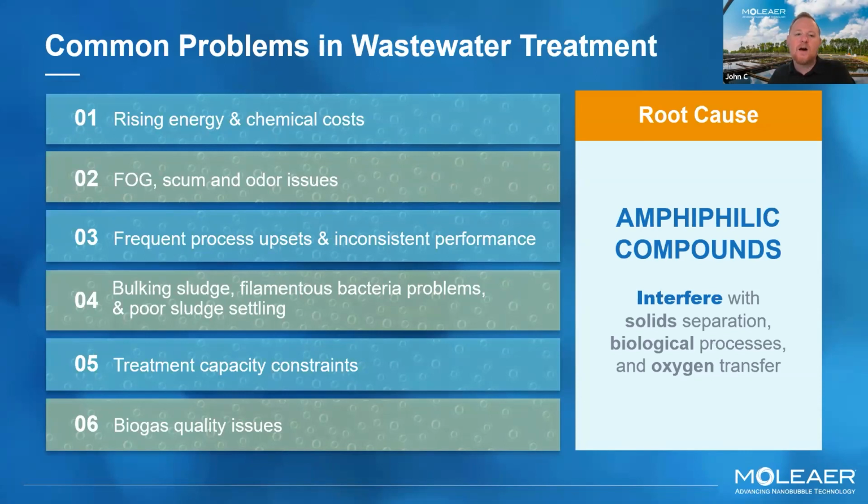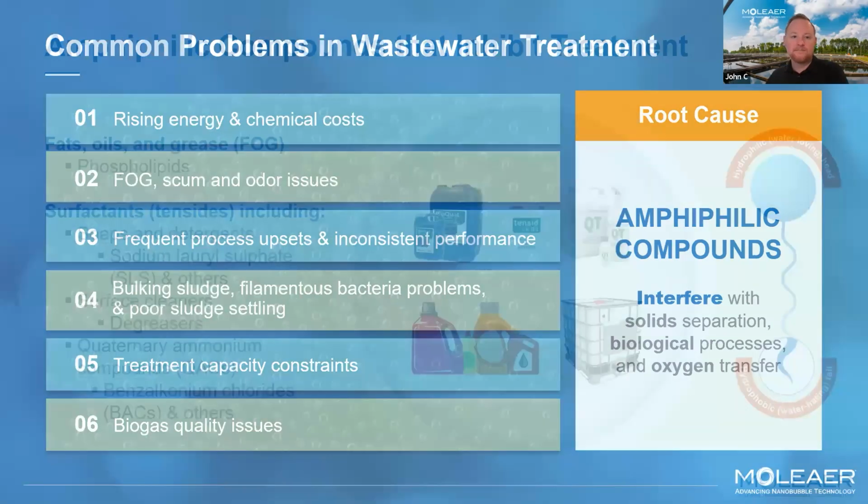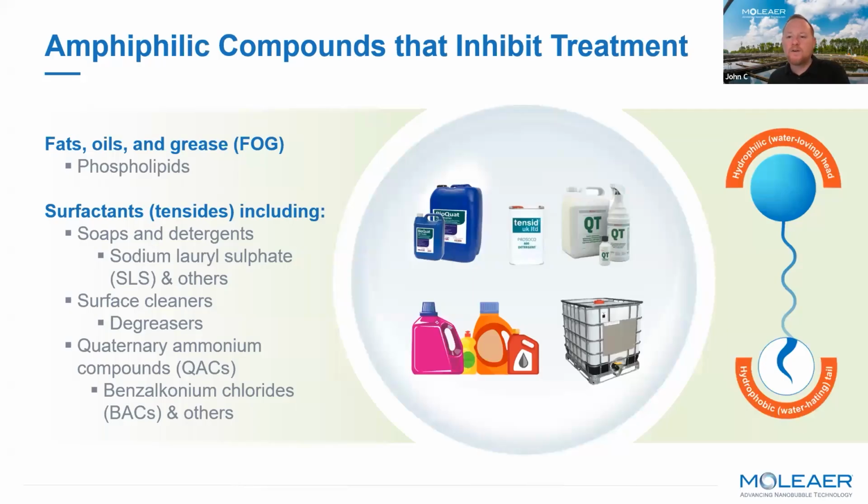So what is the root cause to a lot of these problems? It's an odd word for some of us, but we'll explain it a lot more. These are all caused by amphiphilic compounds. They interfere with solid separation, with biological treatment processes, and most importantly, with efficient oxygen transfer. So where do these amphiphilic compounds come from?